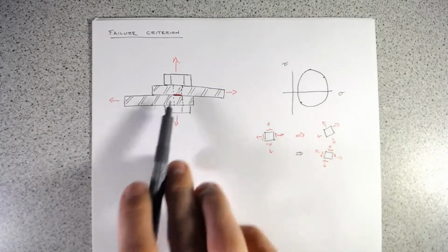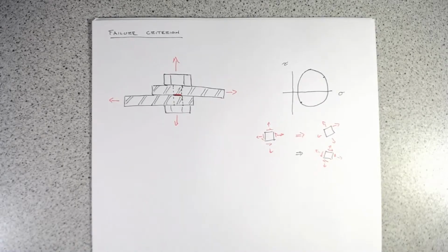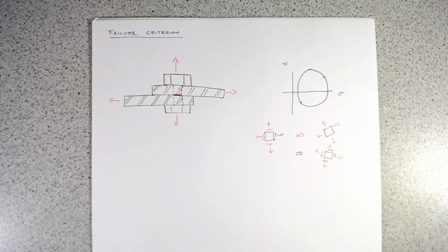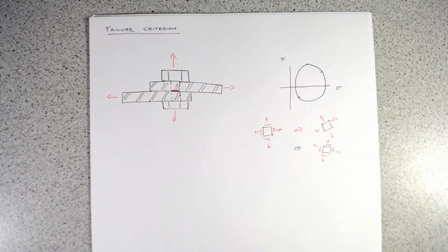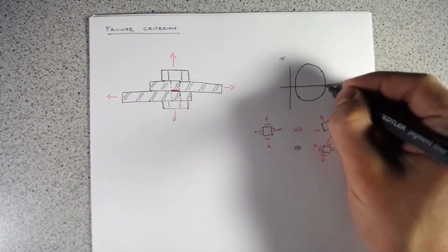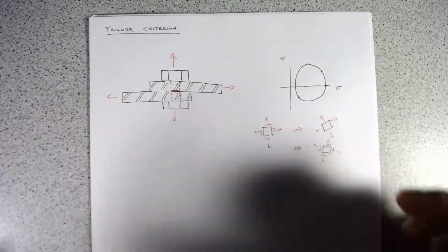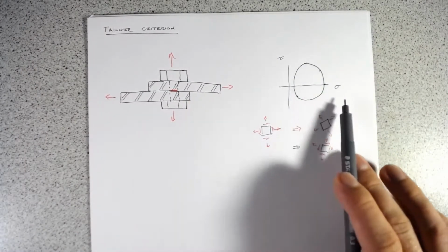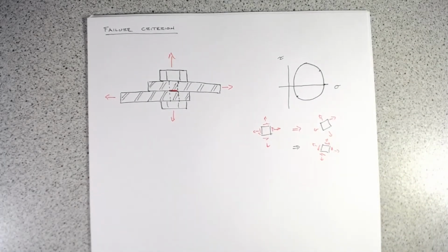So for a given stress state, we have an analytical tool with Mohr's circle to compare it back to these other stress states. How does that help us in determining failure? In essence, we can do simple material tests: we can simply pull on a material, or push on a material in one axis, and then take that stress state and relate it to a whole bunch of others. That's really what we're doing with our failure criterion: relating a particular stress state to uniaxial tests.